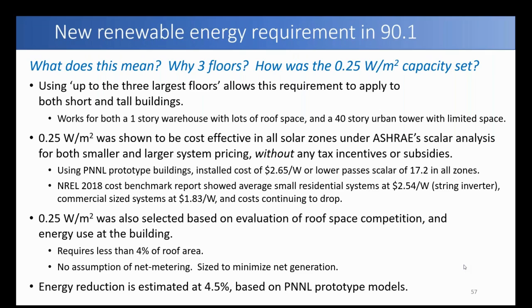We also looked at the capacity and size of this number in terms of what it does for power production on every hour of the day or every hour of the year, not just your cloudy days, but what about on a peak sunny afternoon where it's at max capacity? Where's that energy? And the key aspect here is we are not making any assumptions about net metering. Net metering rules vary across the country quite a bit. So this is sized so that even on that peak sunny day, the energy is being used at the building site. So it's minimizing net generation on an annualized basis and an hourly basis. That means you're not reliant on being tied into the grid. Yes, these will be tied into the grid, but the energy from this requirement will be going into the building, and there's no assumption about net metering.